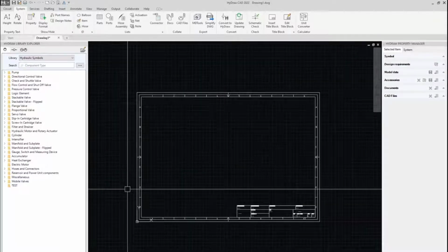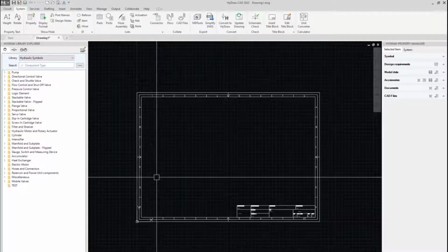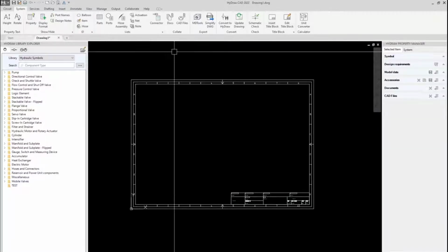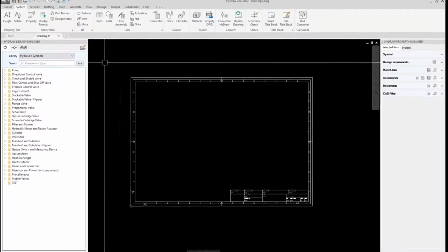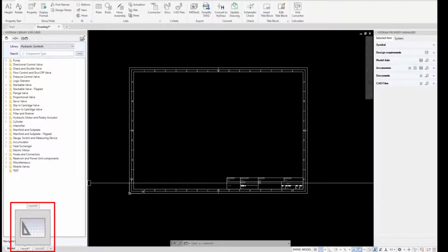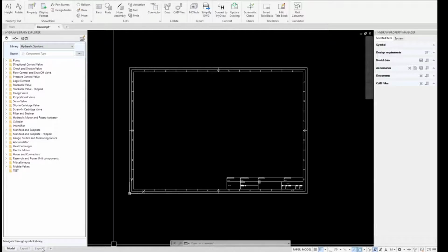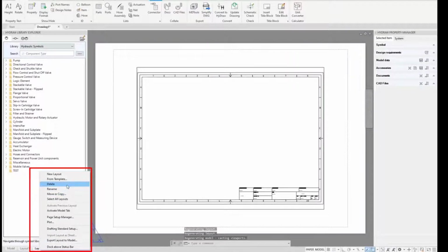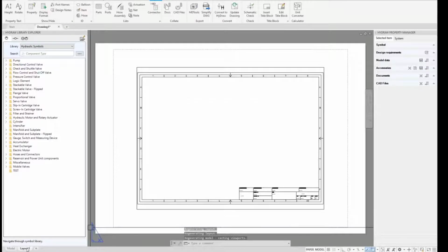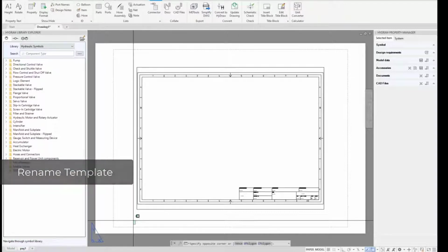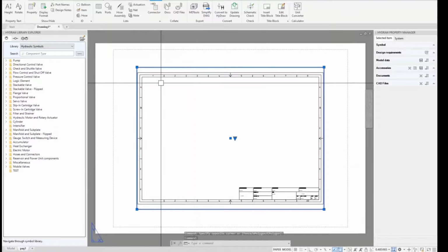Although many of those familiar with the AutoCAD interface will directly plot from model space, I really prefer working in paper space. Paper space is down here, layout 1 and layout 2. Let me quickly show you how to configure my layout in order to print properly. I can just delete a layout that I don't need. This one for me is page 1. I can rename the layout, and I can also delete this entity.